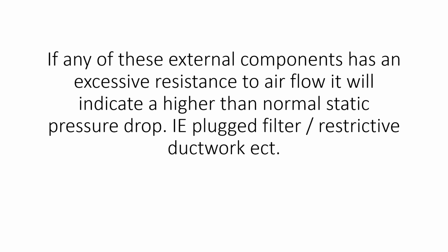If any of these external components has an excessive resistance to airflow, it will be indicated by a higher than normal static pressure reading. Examples are plugged filters or, as we said previously, improperly sized air filters, improper material, or too small or restrictive ductwork. If we have registers that are blocked or dampers that aren't opening correctly, all of these things will contribute to higher than normal static pressures and will then have an adverse effect on our airflow as well as system performance.